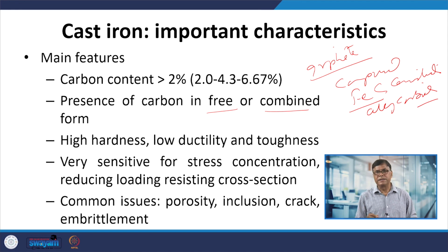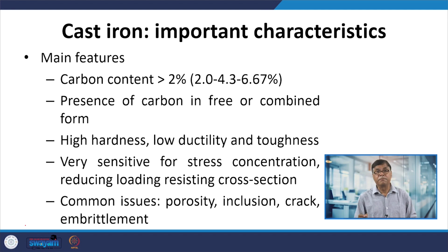Mostly, carbon and iron are predominantly present with a controlled concentration of other residual elements like manganese, silicon, etc. These elements have a marginal effect on the structure and properties. So, what is the factor affecting the form in which carbon is present? Apart from alloying, it is the cooling rate experienced by the molten metal that affects the form in which carbon is present.